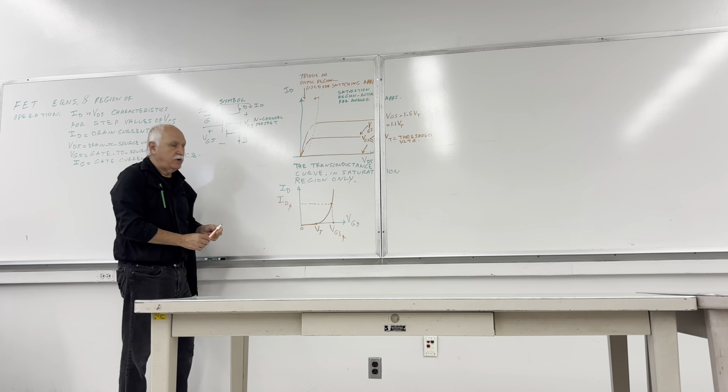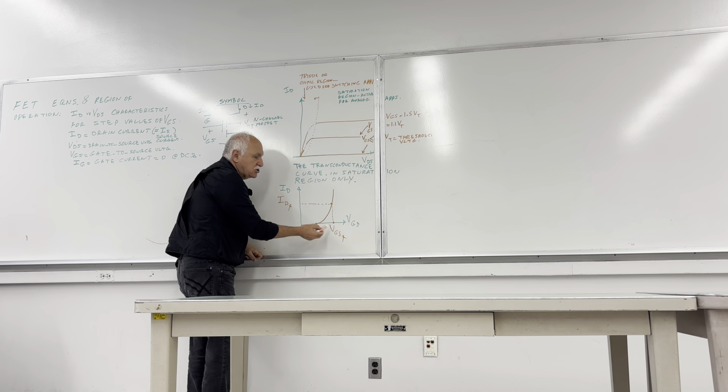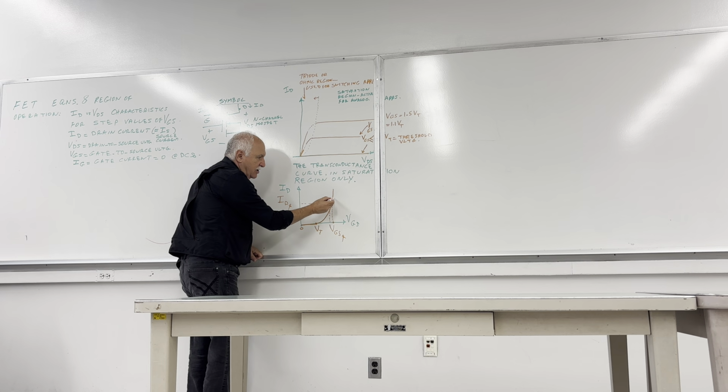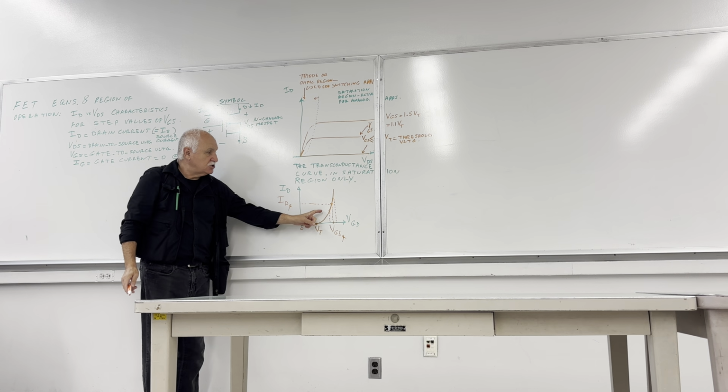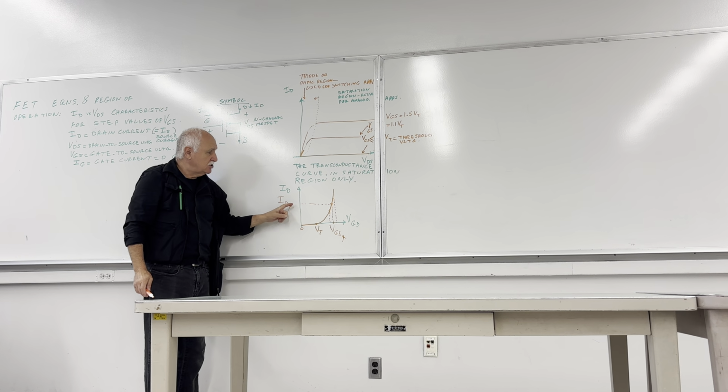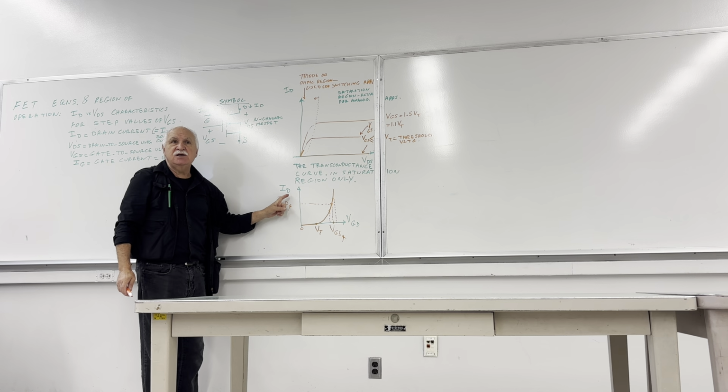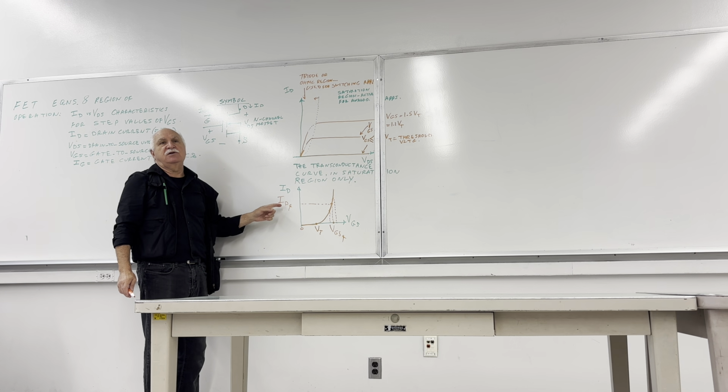Again, same story. If you look at the small changes, quite limited in this range, this chord from the curve could be almost considered like a line. Therefore, for small changes of the VGS, the small change in the ID will be proportional and linear.